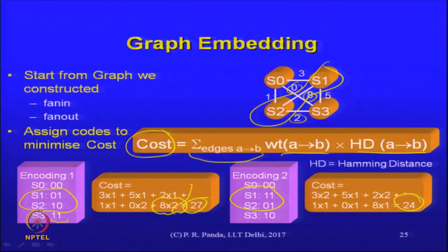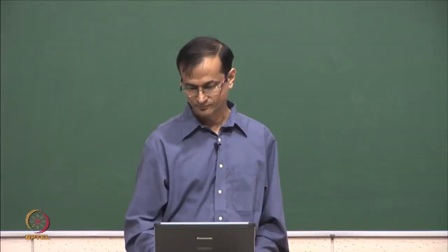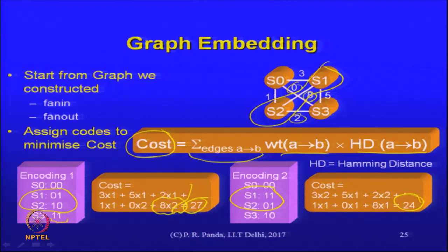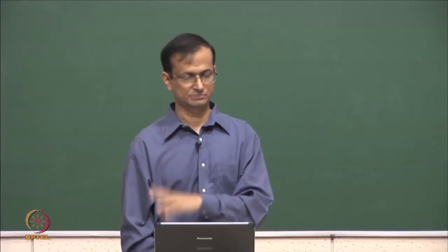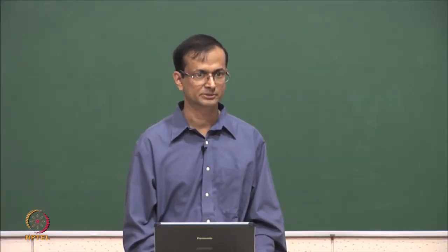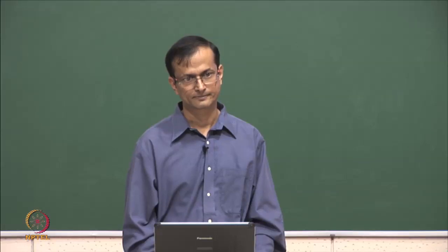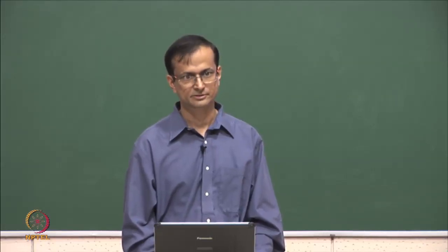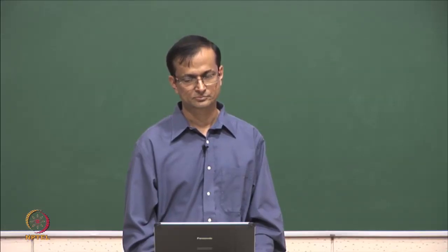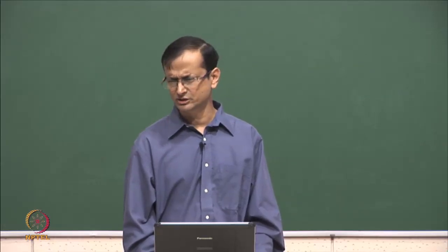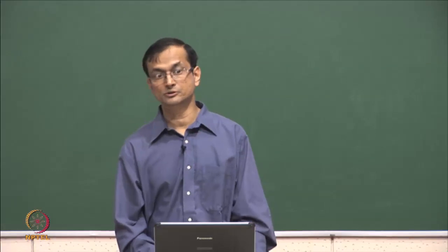The weight of edges were the gain factor. Yes. So that gain we have no control over after we have reached this state. Yeah, we are assuming that this is fixed now. The graph is given, and once the graph is given, it is actually a graph problem. It represents our synthesis being modeled in this way, but graph embedding indeed is a more general problem, just like graph coloring. We were able to translate it into such a known problem, and we can solve it using one of the available algorithms. The gain is a function of the input graph, that is, the state tables. We don't have control over the gain with encoding. Well, we did control it in the sense that it is the output of our quantification.